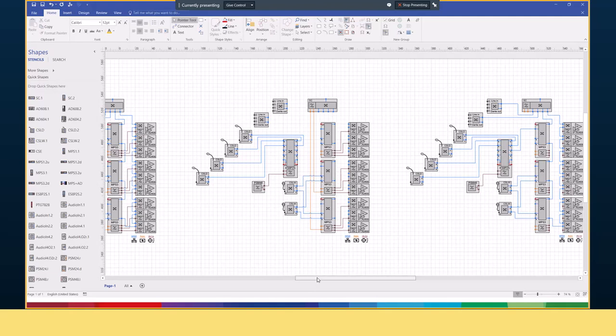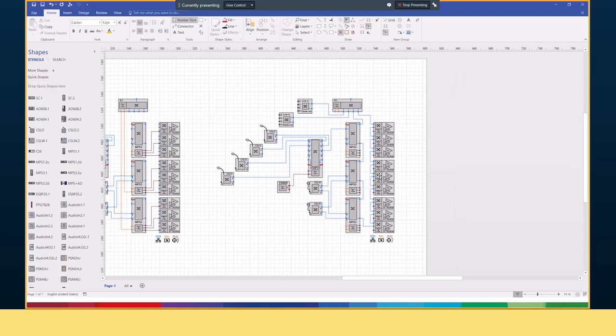And you can have a separate diagram for the network only. And that is actually very, very important, this network diagram. Because in the network diagram, you can very clearly see how your loop is configured, how your loop is connected. So we have 9 amplifiers here, and going back via the MPS, that's 12 hops, and the controller is 13 hops. Yeah, and you know the maximum is 22, including the system controller. Yes, you shouldn't go over that. And if you have more devices, you have to create more loops. You'll see that in the next diagram.